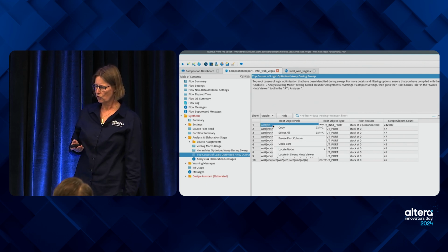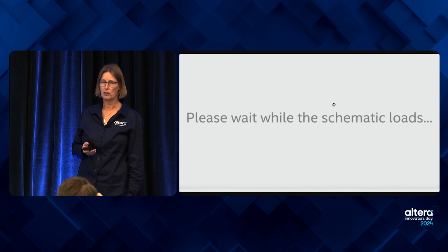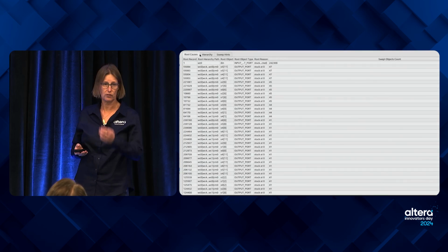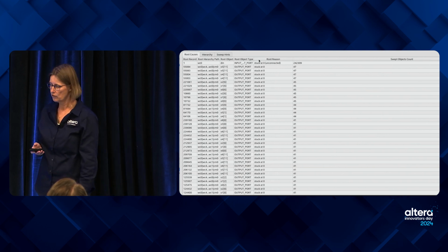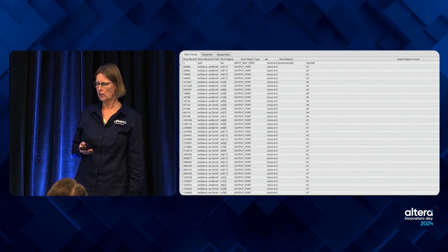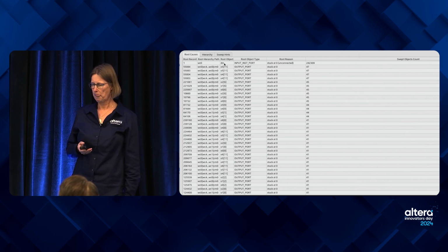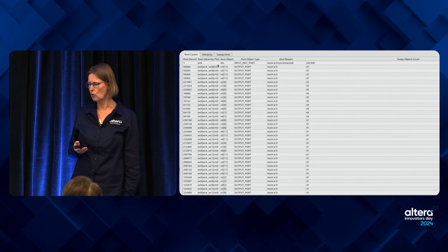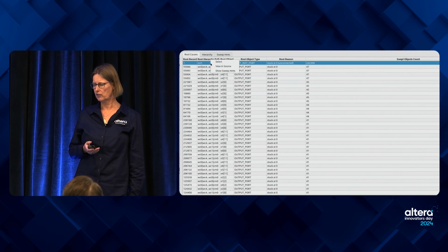So then you can also locate this in the sweep hints viewer. And that loads the RTL analyzer and the sweep hints database. So here you can also see all of these root causes, not just the top 10, but all of them. And still this WC0DIN is at the top. So now you can right-click on this and then actually see all of these 242,000 sweep hints that were caused by this one.